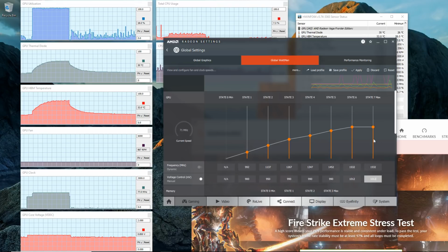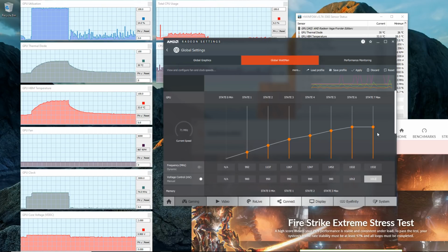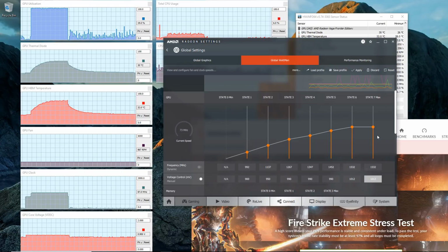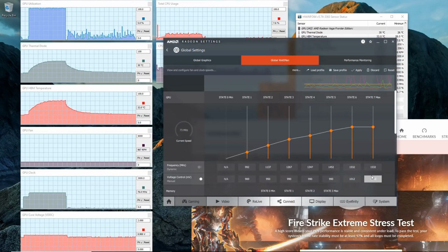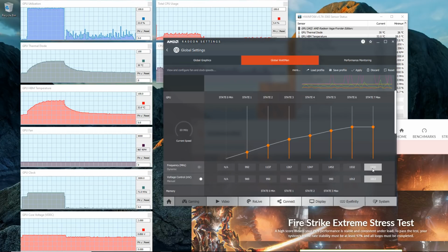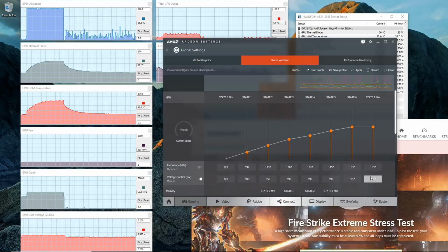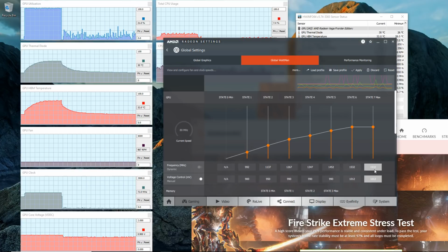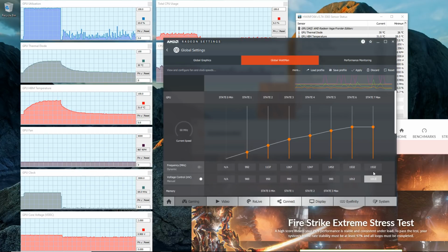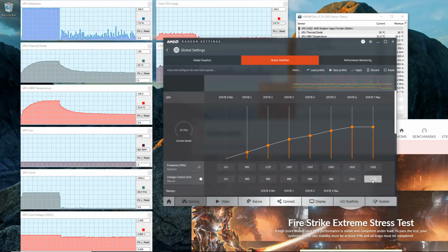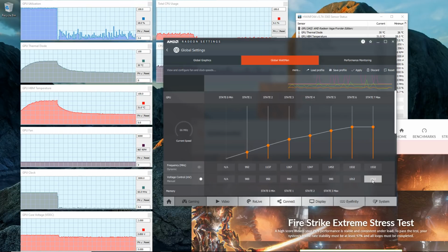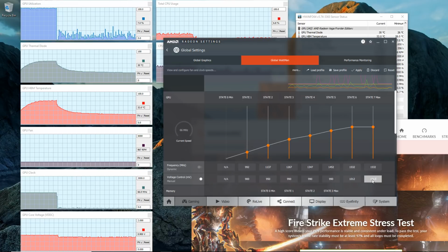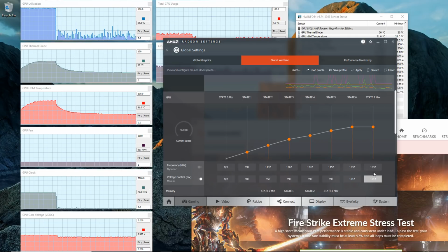And this is the burst performance range of your card. You shouldn't ever expect your card to run here all the time, but you do want the card to be stable when it is in this area. So the stock setting here I think is 1602 at 1200 millivolts. So I know for a fact that I cannot run it at that. If I try to put 1602 here and 1200, it will just immediately reboot my system. It'll hard lock, or it'll trigger a driver reset. It just will not run with this card.